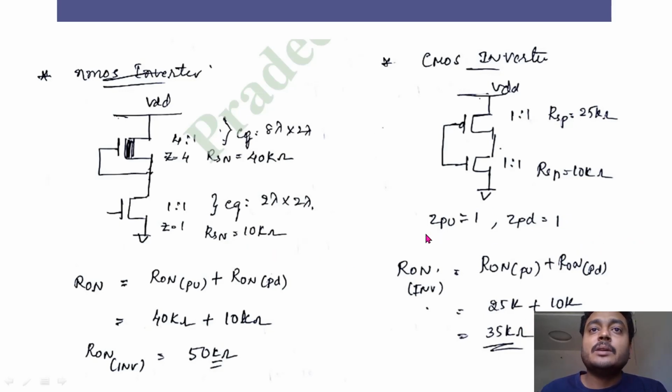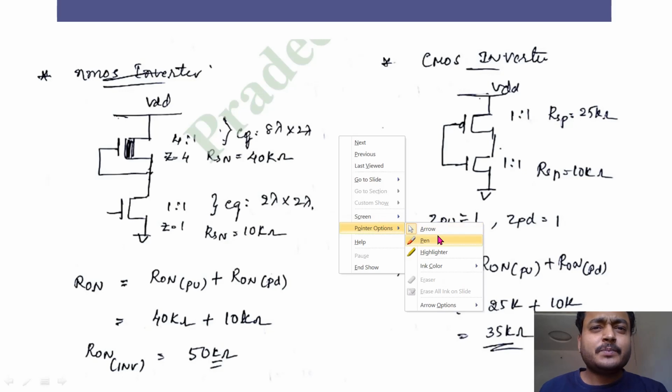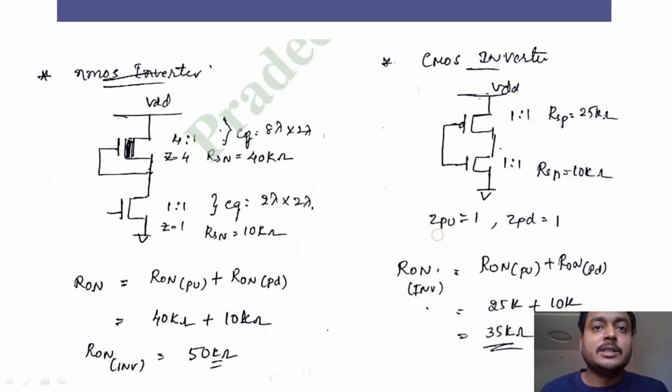So while estimating the resistance of lengthier layers, say we have this slab, this layer, and I want to calculate the resistance for this, I can simply divide it into unit squares. If you divide this one like this, then each is something like L equals W.